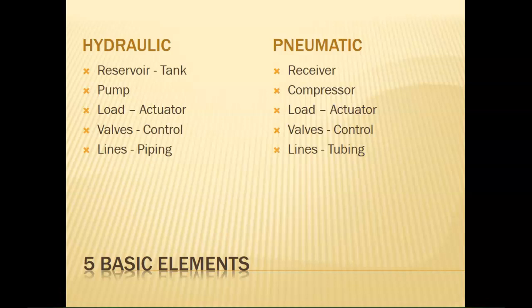For pneumatics, we have a receiver. We don't always have to have one of those, by the way. Now, what do I mean by that? Well, if you've ever seen a little work compressor that people carry onto job sites to work with air tools, those don't have reservoirs. They just run all the time. They don't have that receiver to hold the excess air pressure. What they do have is just a constantly moving engine that is able to compress to a certain point. Does that make sense? So receivers are not 100% necessary. There are several out there that do not have those.